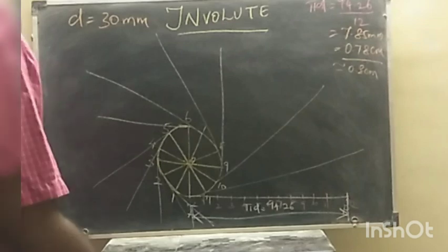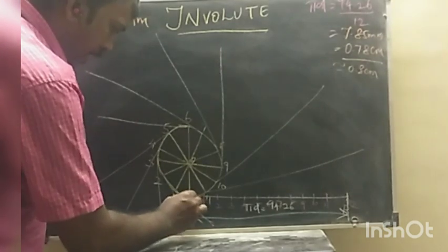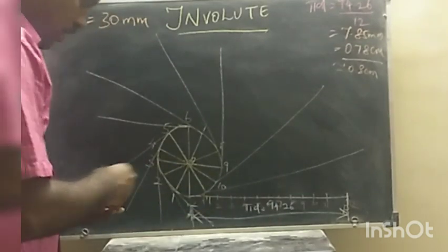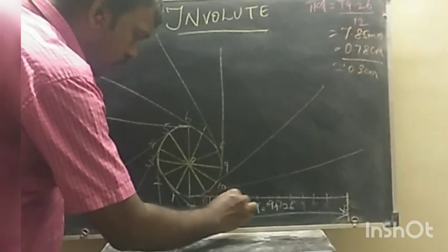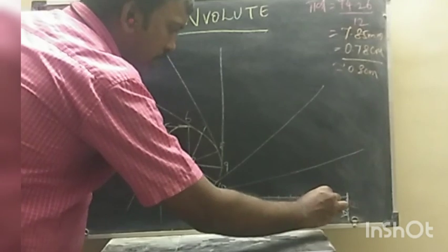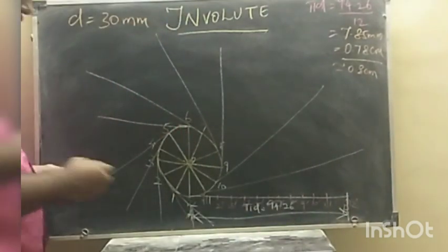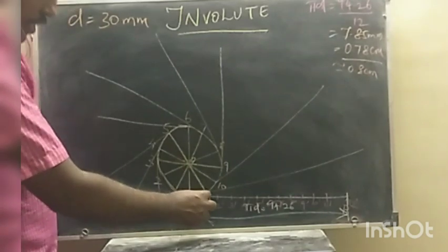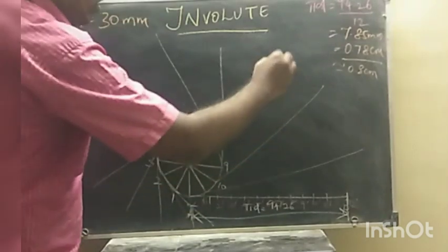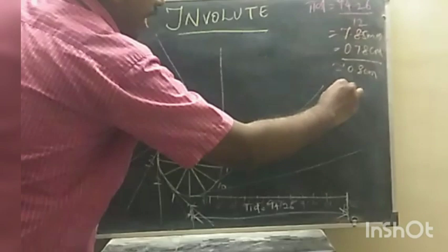Now my next step, guys just listen, this point is A, right? This is A, and here I have also given 1, 2, 3. Instead of this you give 1 dash, 2 dash, 3 dash, so the naming should be unique, right? Give the naming in this manner. Let me take the distance, this point A to 1 dash. In this baseline I am going to take the distance. Let me take it here and mark it here. A1 dash.